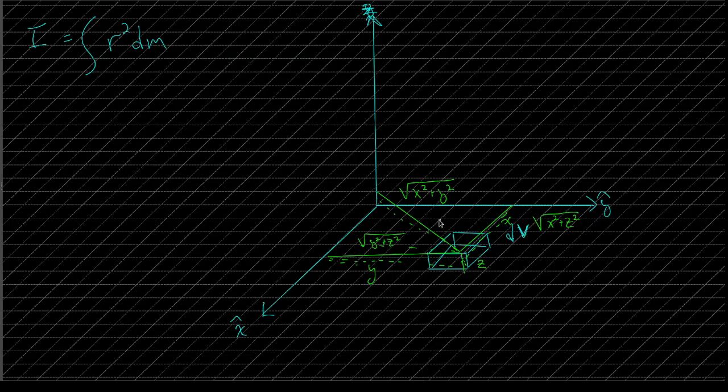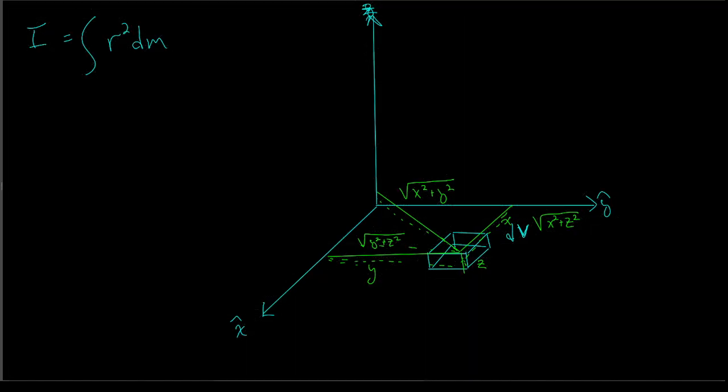And so each axis has a radial component that's kind of defined by the other axes. So if this were rotating or trying to rotate around the x-axis, the lever arm would be the radius defined by the y squared and the z squared components. So if we want to find the moment of inertia about a given axis, so the I about, let's say, the z-axis, or z or x, we'll do x.